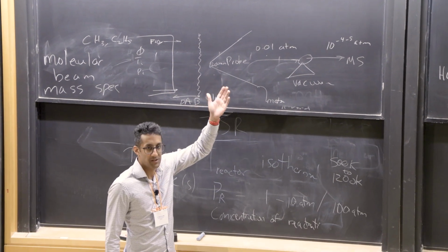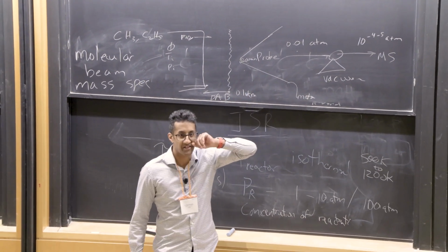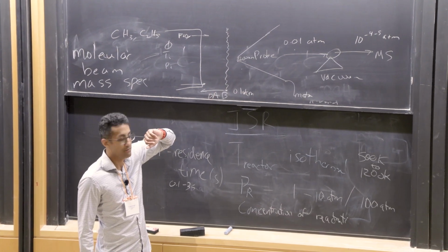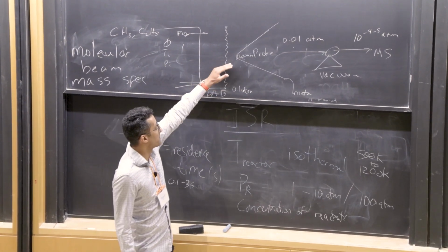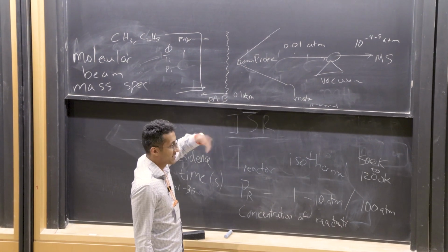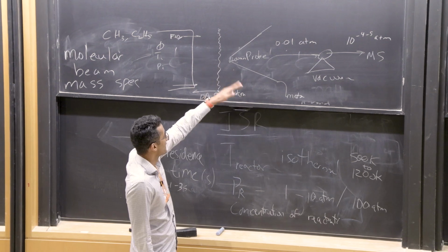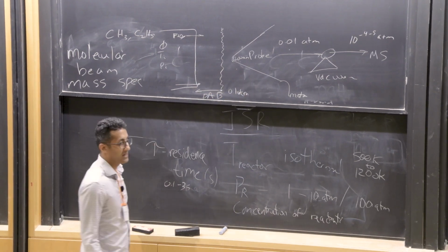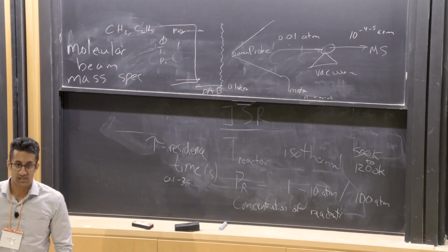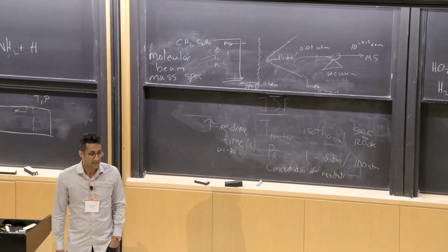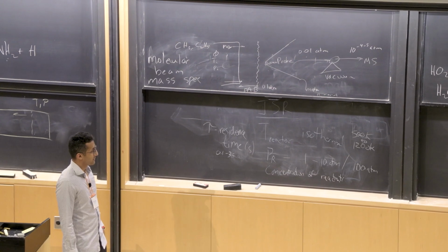You would need to do a full CFD. People have done DNS simulations of it, and they've shown that, yes, it has a major effect on the flame. It has a major effect on the temperature. But we're doing kinetic models. We just want to model this as a very simple premixed burner stabilized flame. We neglect it. You will be assuming the temperature is higher than it really is. And that's, let's say, an artifact of the experiment. How do we deal with that?